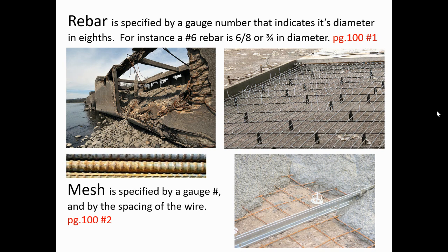You can see what the rebar looks like before they pour the concrete in there. The base is all gravel, so they've got it all set up. They've got their rebar off the gravel, hanging up in the air with those black plastic stands. They have all the rebar wired or zip tied together, so when you pour the concrete, that bar is up in the middle of the concrete slab.